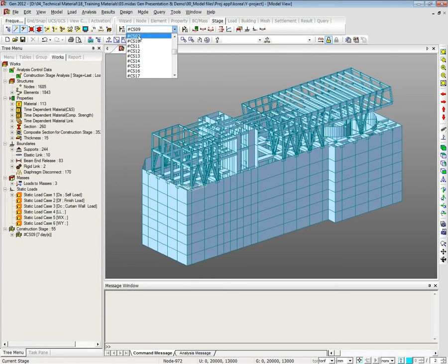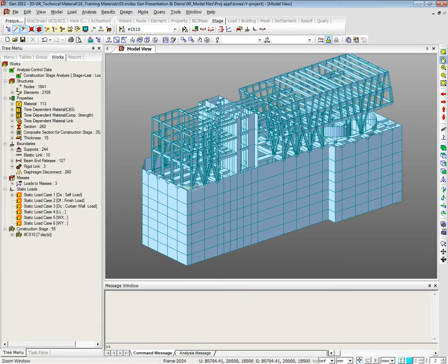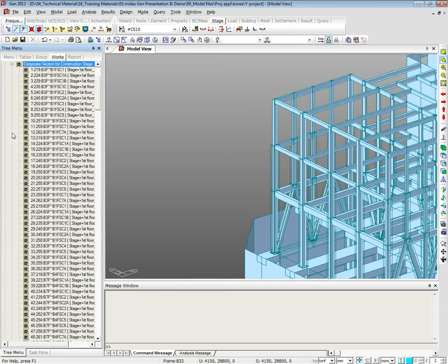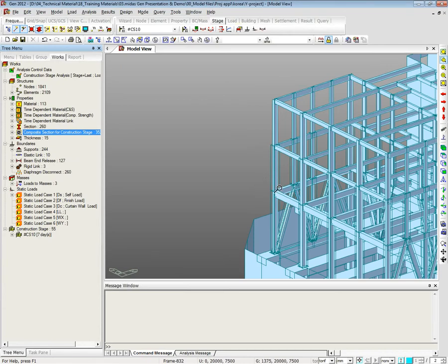And in the next stage also similarly, the column was bare steel in the previous step, and now we have the concrete. This can be considered using the composite section for construction stage data that I will explain later. So MIDAS Gen can consider these different stages for considering the before composite and after composite action.